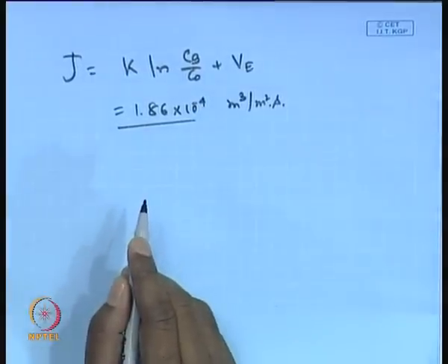In yesterday's problem, we saw an improvement of 20% in flux, but as we discussed in the last class, I would like to emphasize that if you keep increasing the electric field strength, you may not get an unlimited permeate flux enhancement. Beyond a particular point of external electric field strength, the electrolytic solution will start dissociating.